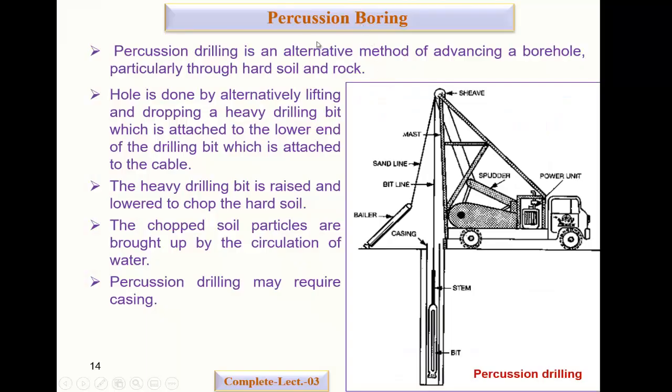Okay, so this is the last drilling boring part of our discussion. Here we will discuss percussion boring, right? Percussion is kind of an advance from the auger. In auger we just do the drilling, right? It is also similar, but here we use beating, by hammering, by using repeated loading.